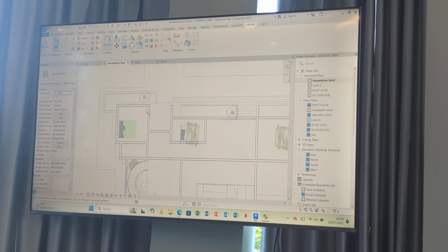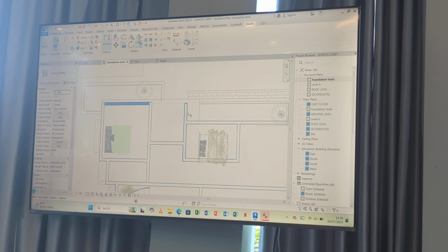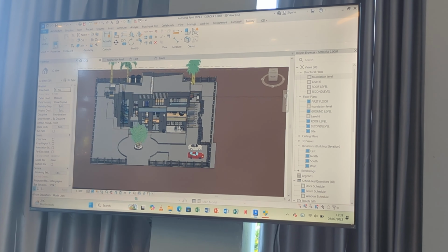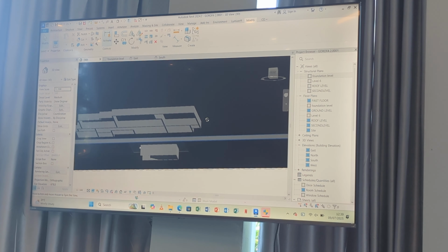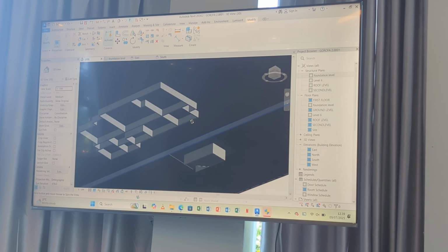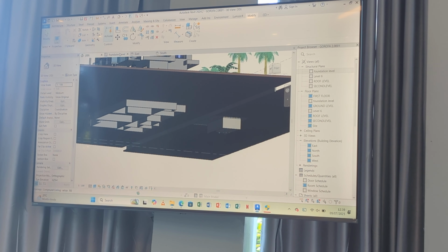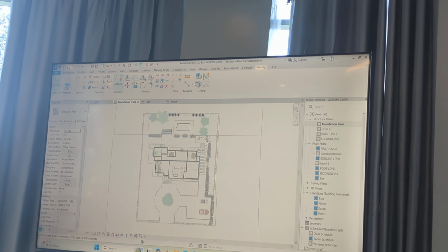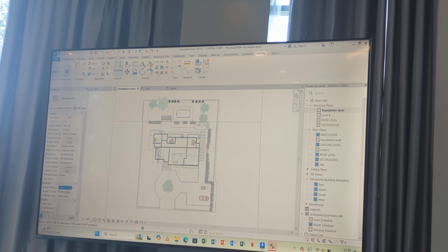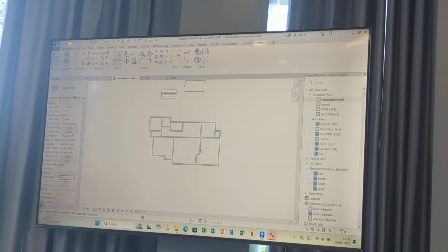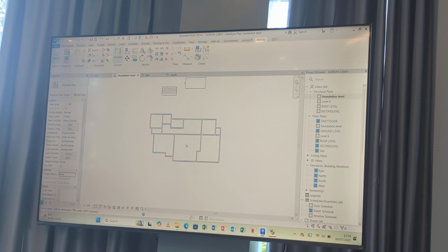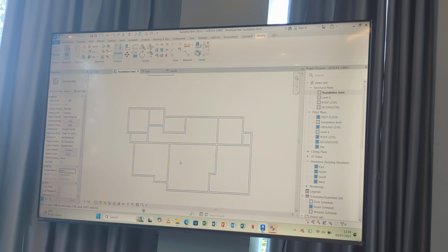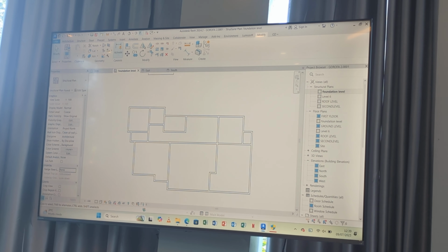So, assuming I've finished my drawing. After you have drawn, you can check. You're going to find that all your walls are below. You see this? We are now seated on foundation level. Remember that was your base range. After you've done this, you can hide. Change this base level back to none. Okay? Now this is what you have below. Now I have this structure below. I have put my plinth walls. Now I proceed to put my concrete strips. Concrete strips just come here.